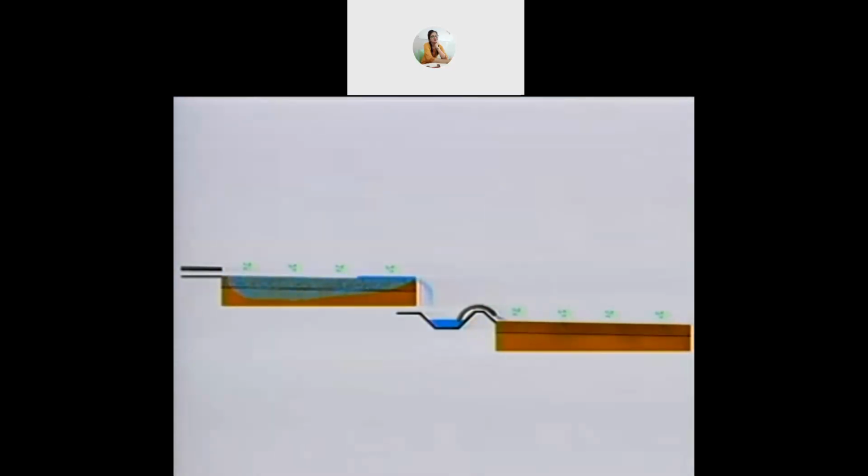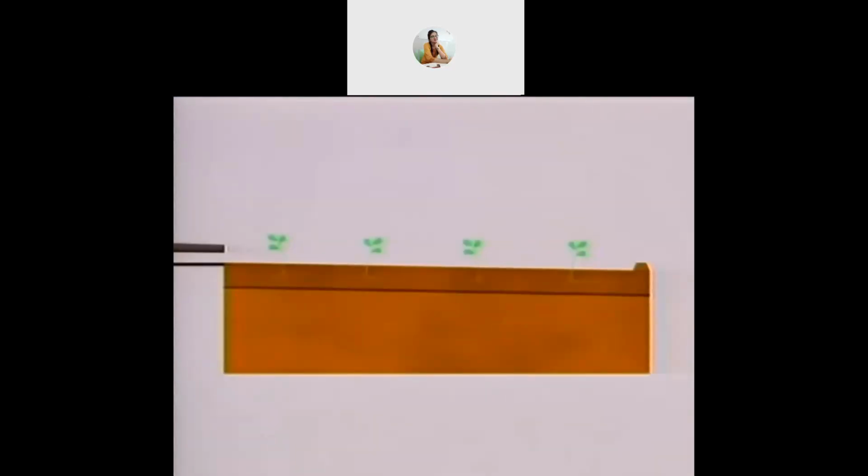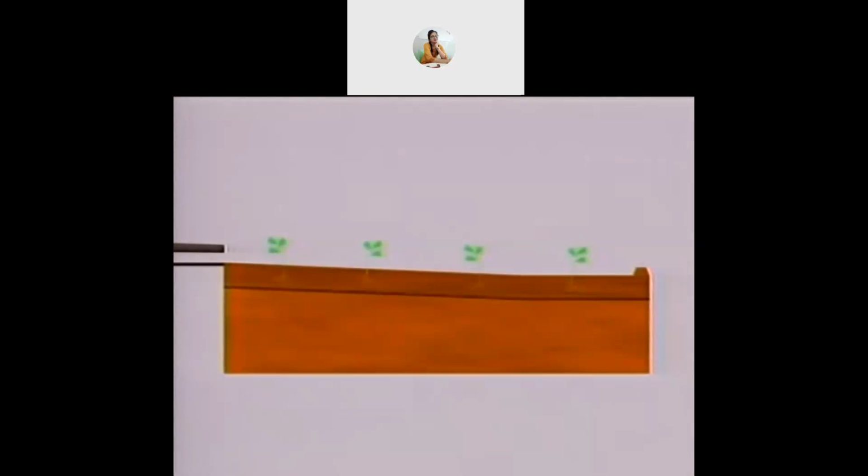The disadvantages are: standing water can harm plants mainly by reducing the respiration of the roots, it is fairly dependent on soil slope, erosion is frequent in the grooves, and lastly, loss of water occurs due to percolation. This is a figure of surface irrigation.